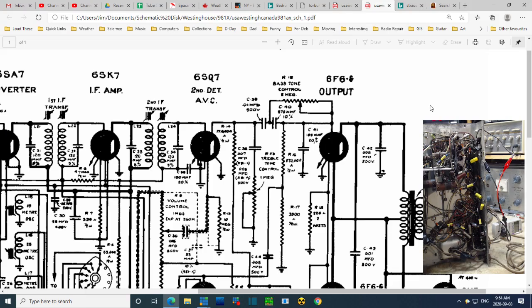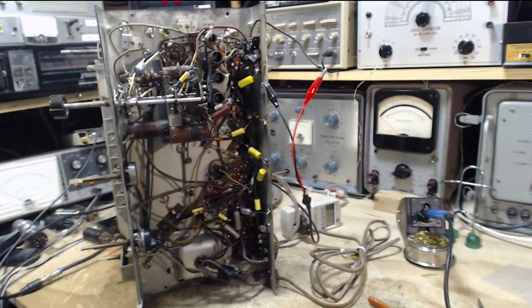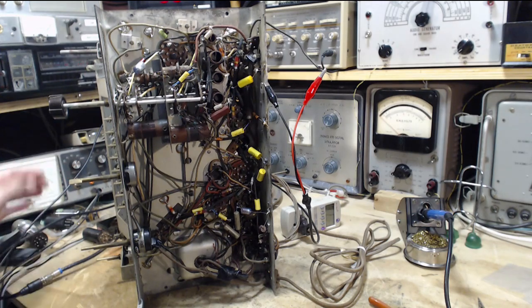Radio's not really humming. I have it on its big speaker, so I'd hear it if it were humming. Where are we at now? Now we're at the run through, a check of voltages on the tubes, and then we're ready for alignment. So tube voltages should be good. We're on the 150 volt scale, but there's over 250 volts in there, so we'll go on the 500 scale, so 250 straight up.